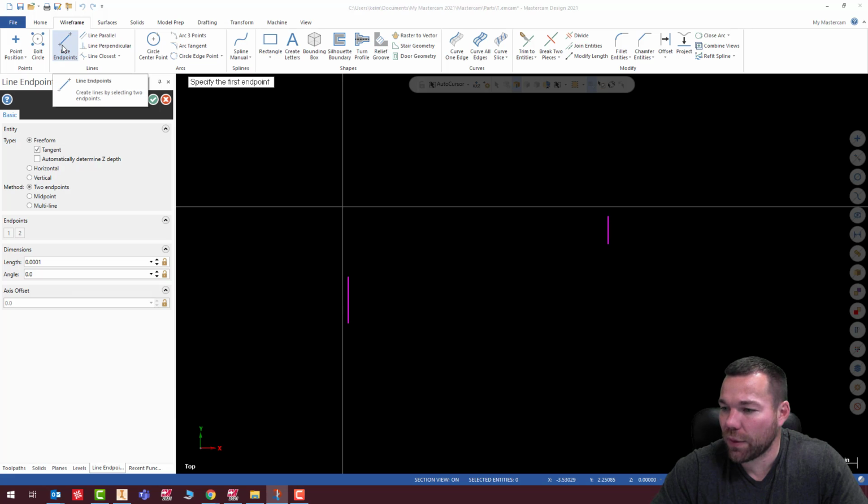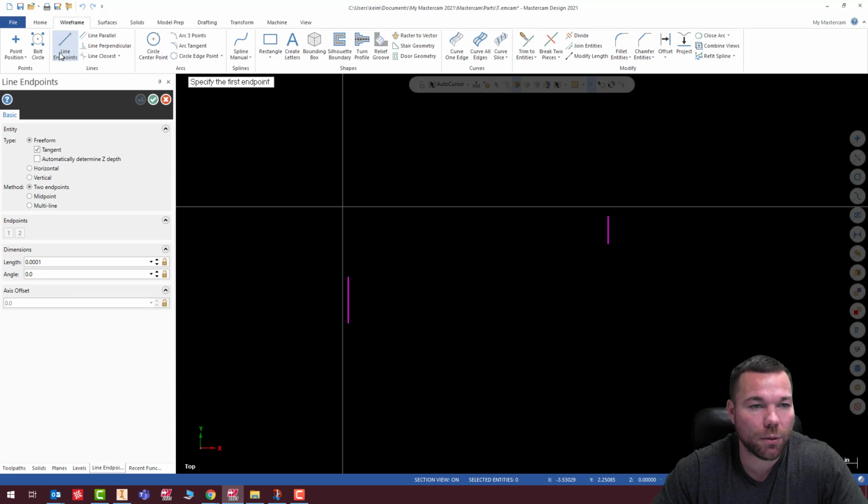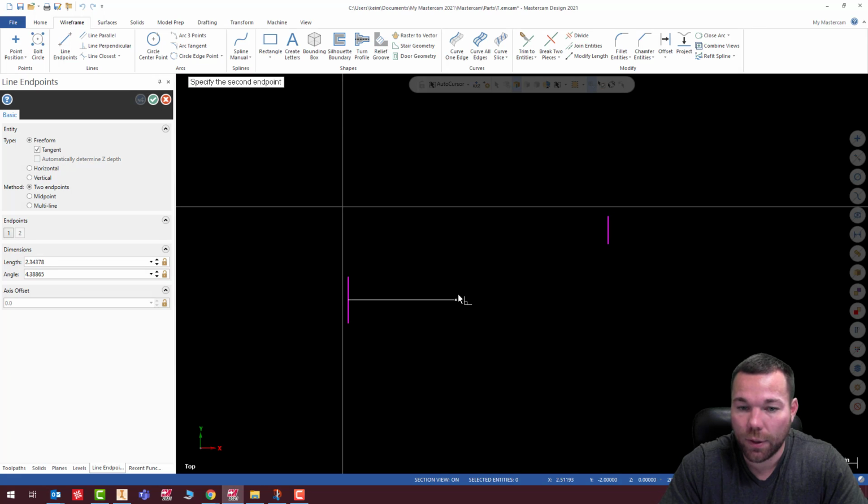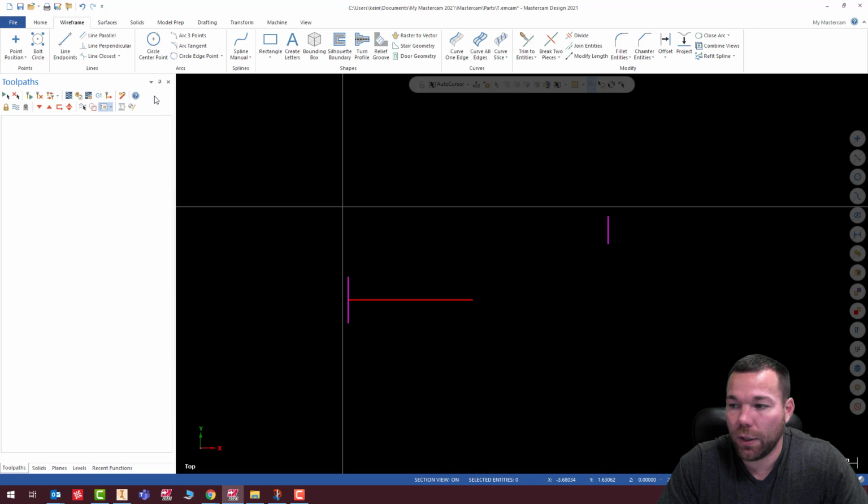All right, so I'm going to create this line. And let's see, it's at -2 inches. -2.0. Actually, that's the Y. 0.125, comma, -2.0. And I'm just going to draw my line there.